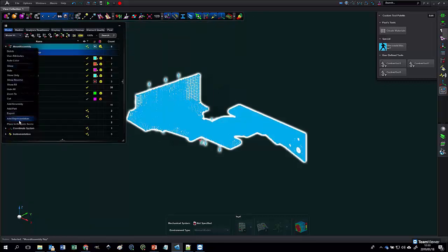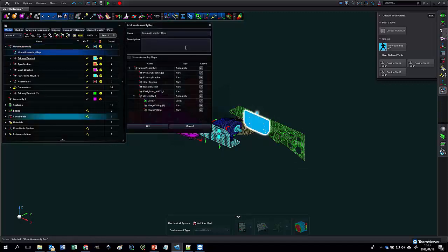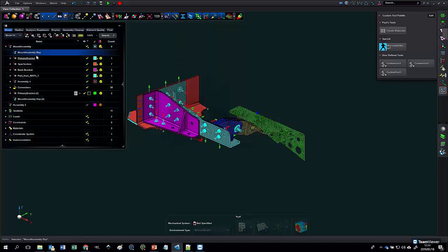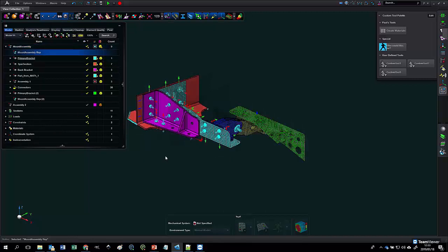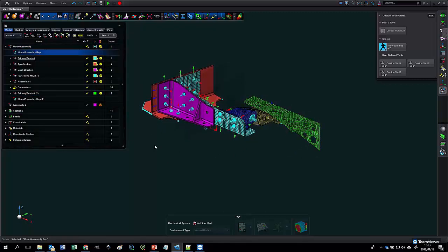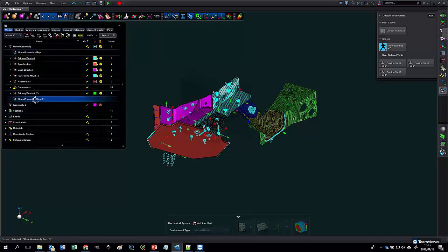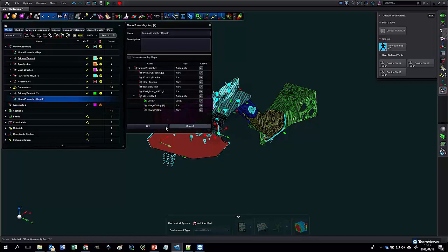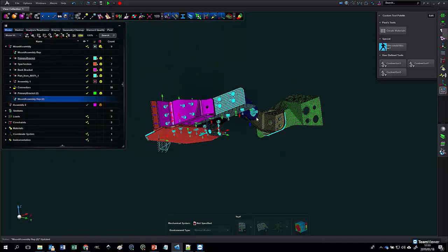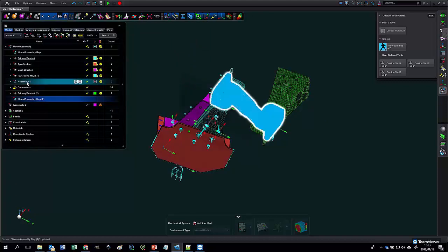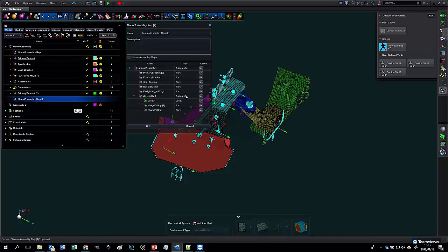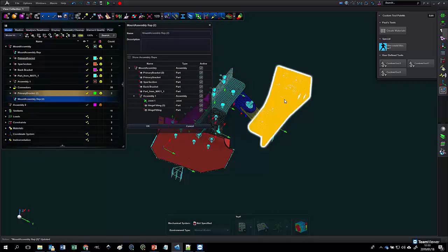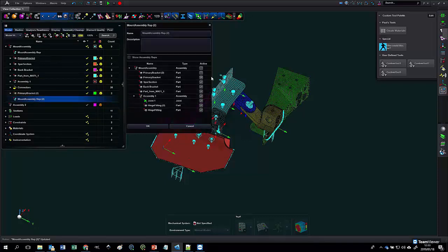If I were to create a new model rep, I'll just say add representation here at the bottom. And by default, everything will be included. Now I could have just solved it directly. I don't need to create a model representation, but if I want to exclude stuff, I need to create a model representation or solve them individually. But this model assembly at this stage now has everything included. Or as previously, when I only modeled that assembly, I could have just solved that, or I could just say, okay, I want to create a model assembly that excludes this bracket, primary bracket number 2 over here.